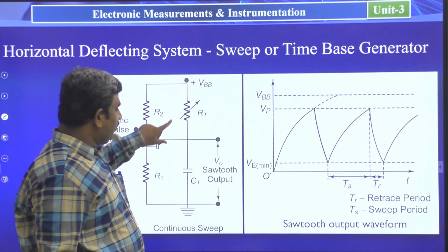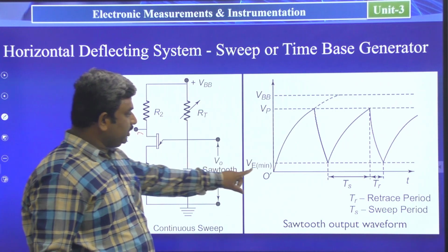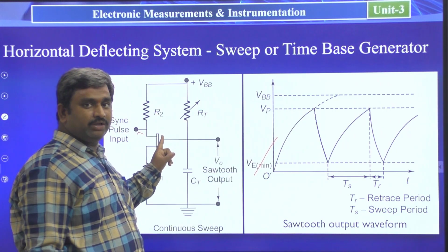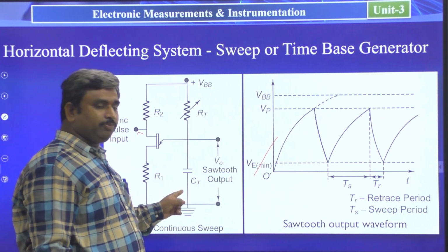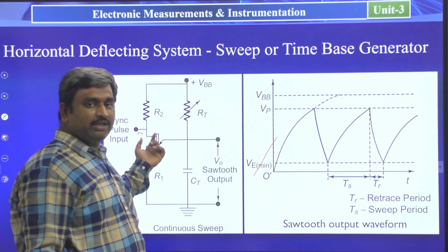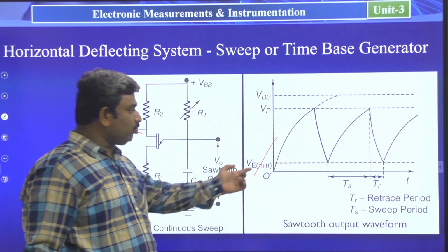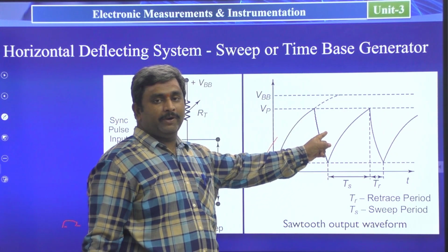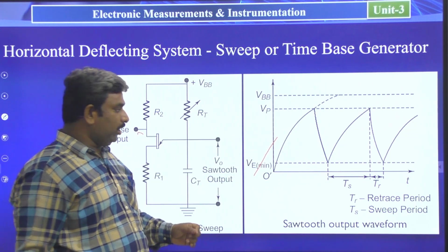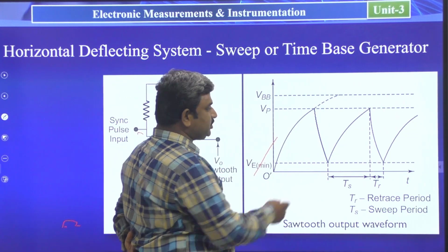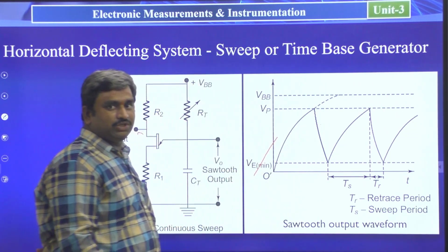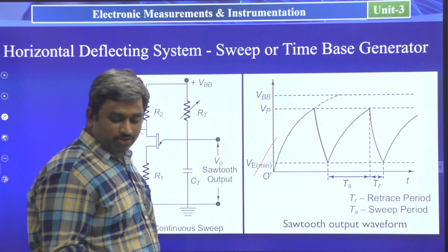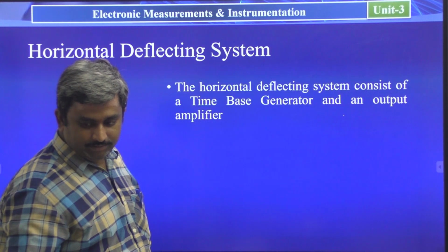So here, whenever the UJT is in the off position, the capacitor is going to be charged up to Vp. Whenever the UJT is in the on condition, then the capacitor is going to be discharged rapidly. At this situation, the UJT transistor is on. So first the off position of the transistor, then the on position of the transistor. Now in the next concept we will see.